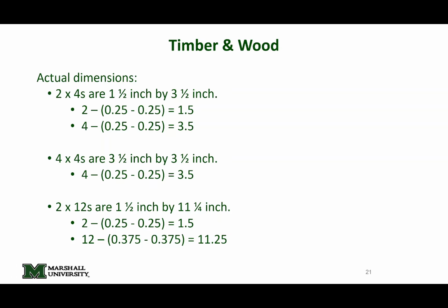So one of the things you'll see, for example, in the timber spec next semester is a lot of section properties for S4S lumber. And it's like, what is S4S lumber? It means it's surfaced on 4 sides. So you might see surfaced on 4 sides, surfaced on 2 sides, et cetera. So that gives you an idea of why that is what it is.